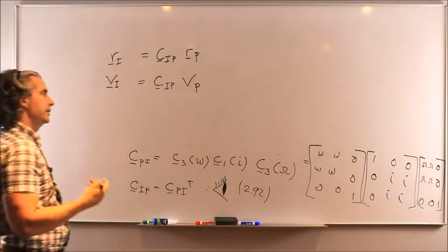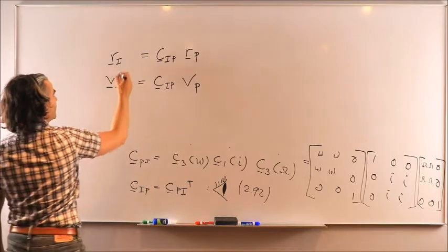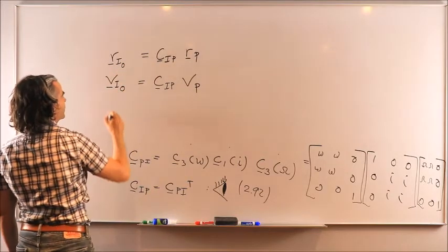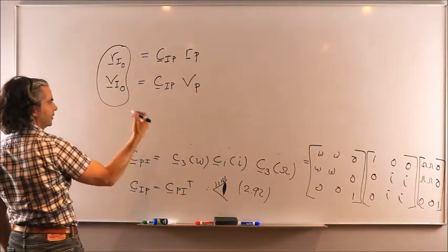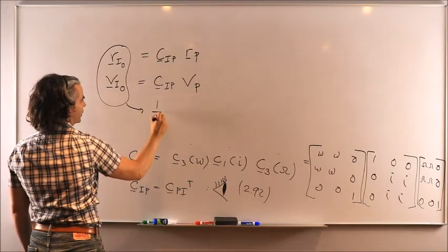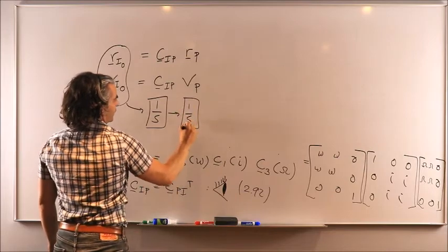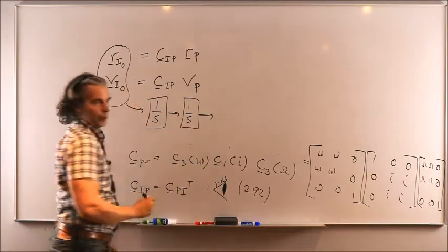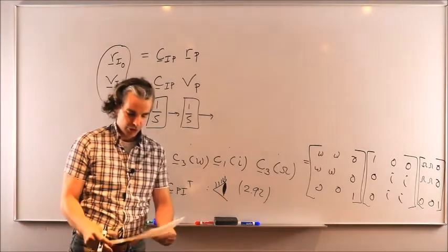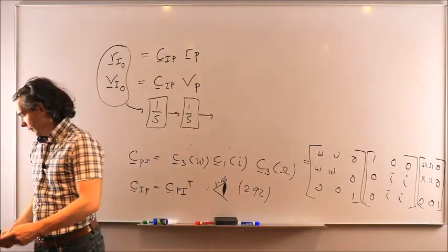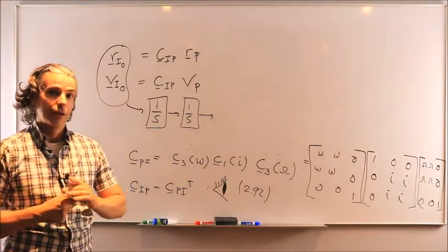If you had chosen t equal to 0 to initiate the entire procedure, then what you get is what you can use to initialize, or set the values at t equals 0, of the integrator blocks in dynamics that will allow you to generate a three-dimensional orbit. Okay? So this is how you go from orbital elements to position and velocity in the inertial reference frame and how to use it practically to simulate an orbit in MATLAB Simulink.